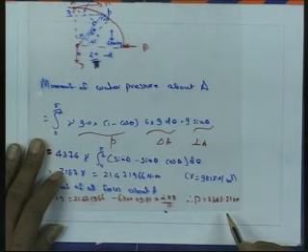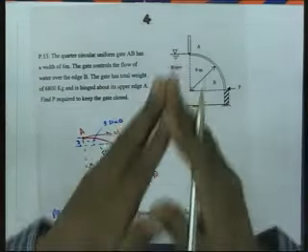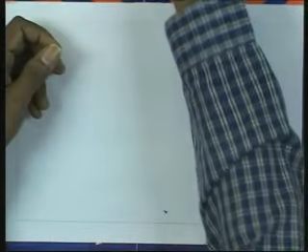2343.31 kilonewton. So like this we can consider all the forces acting on the gate: the water pressure from this side, the force which we have to apply to keep the gate closed, that P, and then the weight of the gate. Like this we can solve various problems to find the resultant force, center of pressure, and its various applications, as we have demonstrated in all these examples discussed here.